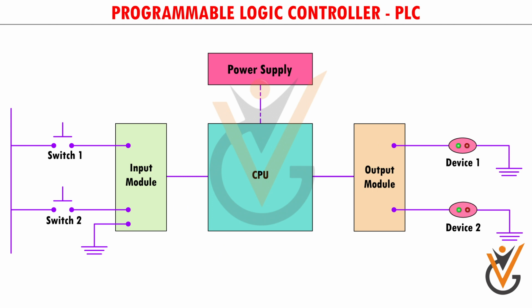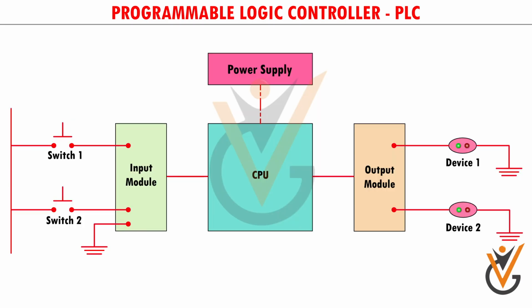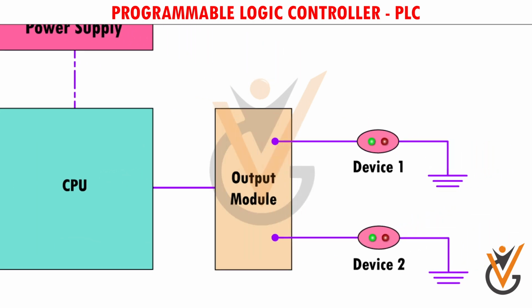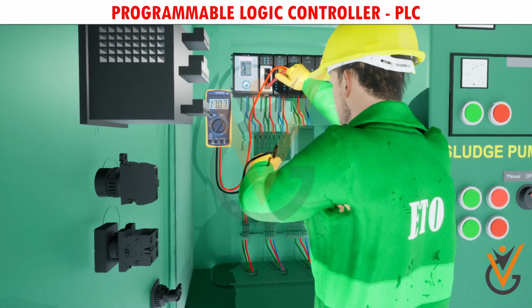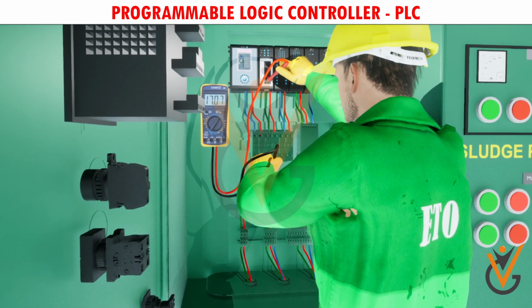There is a problem with the module if an output rung is activated while the LED indicator is turned off. The module connectors are to be checked for poor contact or misalignment when there is no malfunction found in the input or output module. Lastly, check the connector terminals and cold solder joints on module terminals for the presence of broken wires.